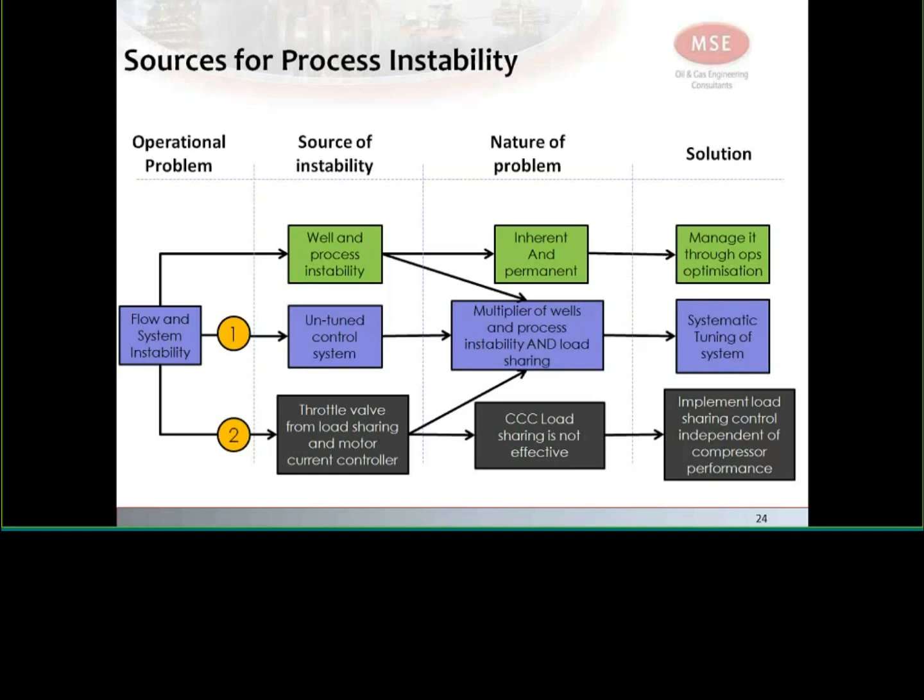The second thing that we found out is that the anti-surge control system was not tuned properly to the demand of the process itself. And frankly, because there are 3 different stages of the compressor and 2 different trains of compression, and the overall interaction between the trains, it makes it really difficult to go offshore and try to play around with the control system and tune it.